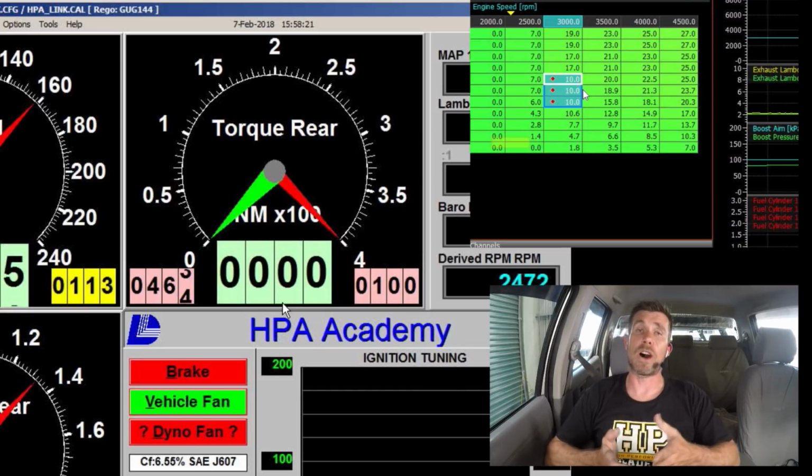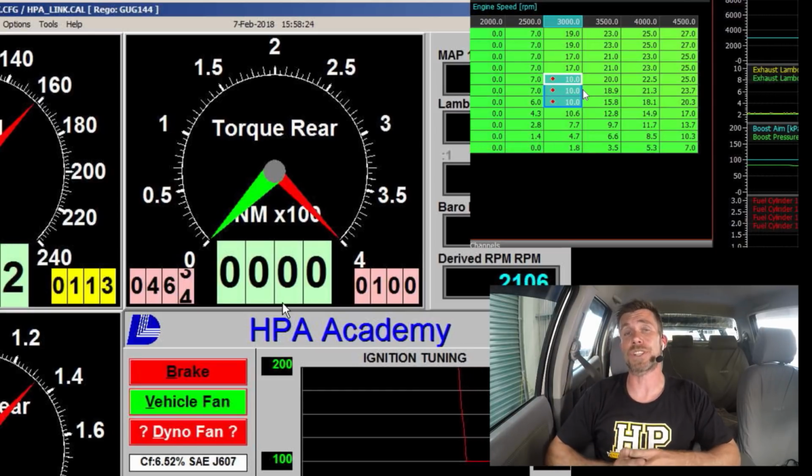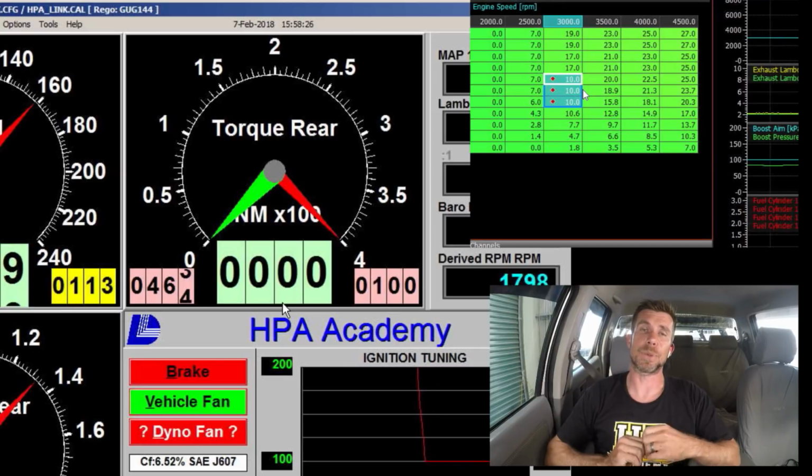So the process there of optimizing our injection timing is really quite similar to the process of optimizing our ignition timing in a gasoline engine. What we're doing is moving that injection event around in order to make sure that we're getting peak cylinder pressure occurring in the correct point in the cylinder. The problem with this, as I've mentioned though, is that if we advance the timing, we start our injection pulse too early in the engine cycle, this can result in damage to the engine. So this is something we do need to really tread carefully with. We want to be really careful with that.